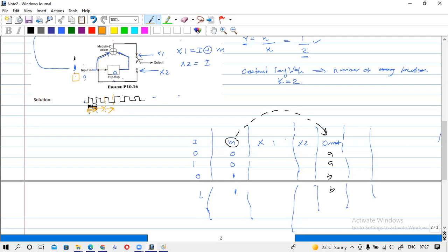At the beginning, the input flip-flop has 0, and this M also has 0. Then we push 1 here, and this will be replaced with 1. What happened to this 0? It will be pushed to the other flip-flop, and that flip-flop's value will be 0. Understood?